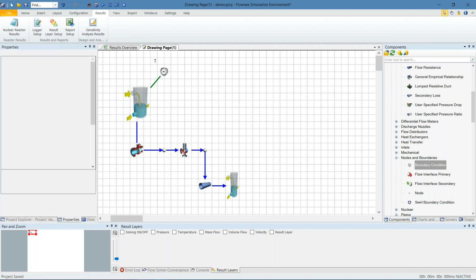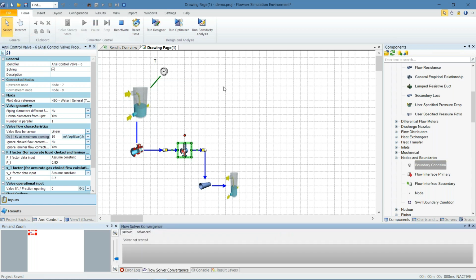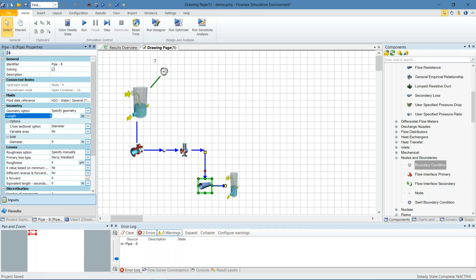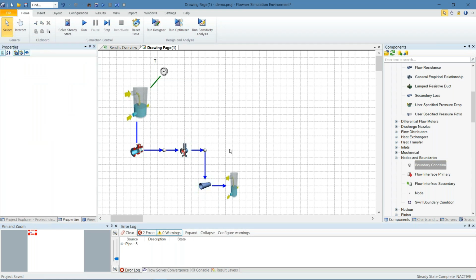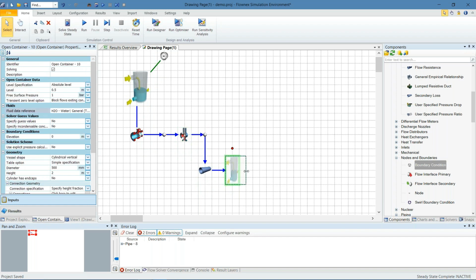Okay, so at this point, I'm relatively confident that I've input everything in my network, and as I say that, I've realized I haven't specified this valve. So we need a CV for our control valve. For now, I'm just going to choose 10, and then we should be able to solve our network from there. So let's solve steady state. Oh, okay. As I do this, I've forgotten that I've missed the inputs on these components. So it's myself trying to get ahead, perhaps rush a little bit.